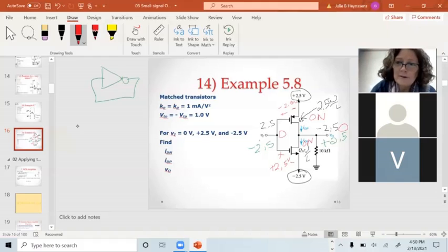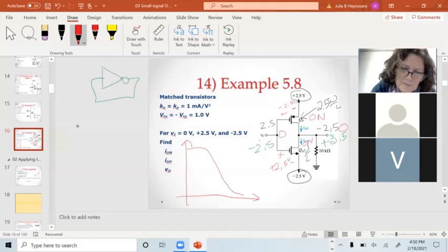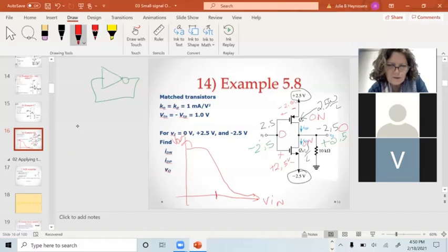And you can think about this, and I was actually talking about this in 490, why I think you should take 380 first. As you think about the voltage transfer curve for an inverter, this is my VIN and this is my V out. When I'm at VDD over 2 on the input, halfway in between, my output is also going to be at VDD over 2.